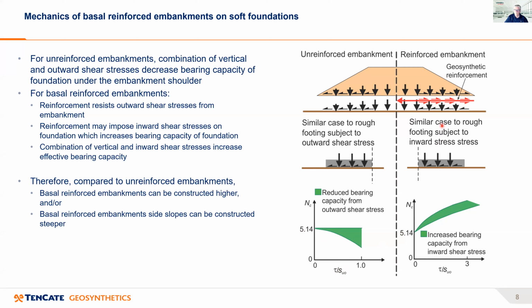Now let's turn to the reinforced embankment case. And what we have, again, is the vertical loading of the embankment and the horizontal outward shear stresses. But now we're introducing a layer of reinforcement at the base of the embankment. And what this reinforcing layer does is it changes the outward horizontal shear stresses: it absorbs those, and it imparts inward horizontal shear stresses on the surface of the soft foundation.